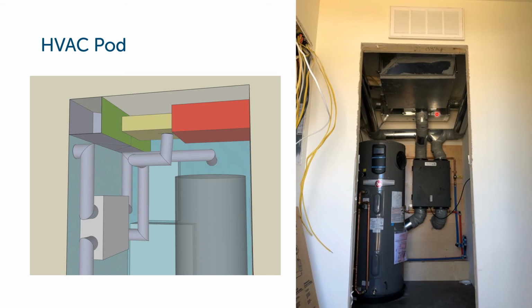And here is a small supply duct plenum. And here is the main supply duct going out this way. This is the ERV. The fresh air goes through the injection port right here into the supply plenum where it's mixed with the air from the air handler and goes out into the supply.